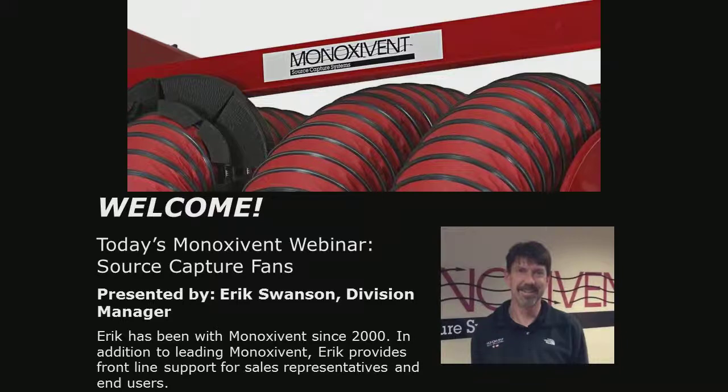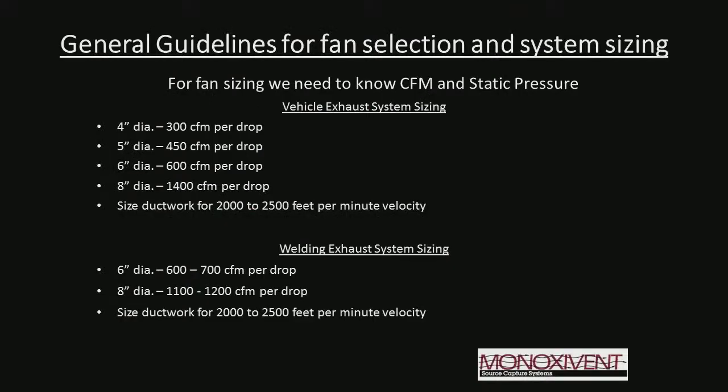Thanks, Brian, and thank you all for attending the seminar. Today, we will be talking about fans, primarily the fans that we offer and that are appropriate for our systems. Obviously, what we need to know before we can even select the fan is the required performance for the system. That would be both CFM in regards to airflow and static pressure, what the fans will be working against. For today's discussion, we'll talk about vehicle exhaust systems and welding exhaust systems and some of the CFM requirements for those particular types of systems.